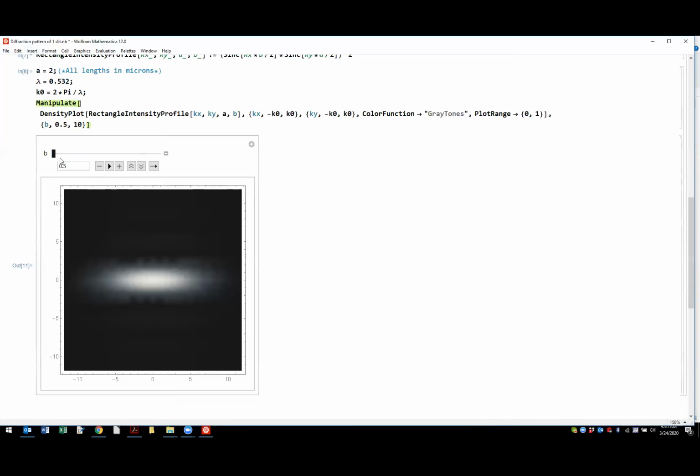The idea of a spatial light modulator is that they have pixels. They usually do them nowadays as mirrors. There's two ways they could do it. They can either use electro-optic effects to change the refractive index of each pixel. What that means from a side view is that you get a phase shift.